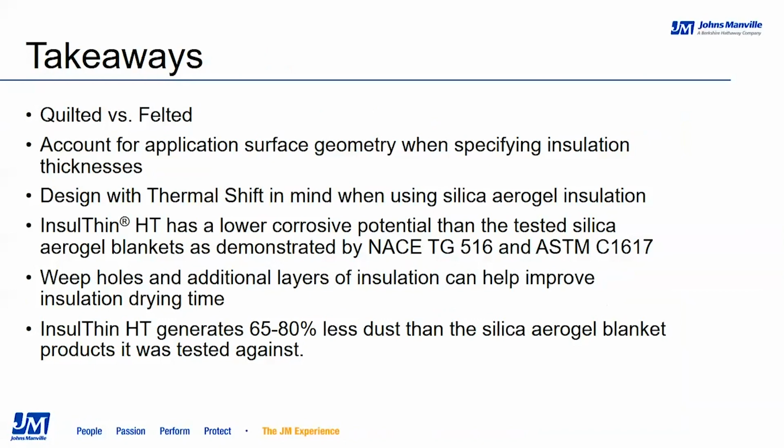Also keep thermal shift in mind if you're designing a system with Silica Aerogel blanket insulation. Now, this can help ensure that facility operators don't have to go back and retroactively correct systems that have been installed but aren't performing as expected. Also, if you have a system that is insulated with Silica Aerogel and you find that it's running hotter than you expected, thermal shift may be the culprit, and that's something you want to consider as you decide how you're going to address your hotter temperatures.